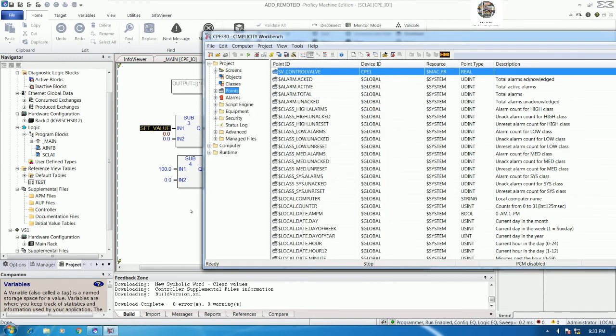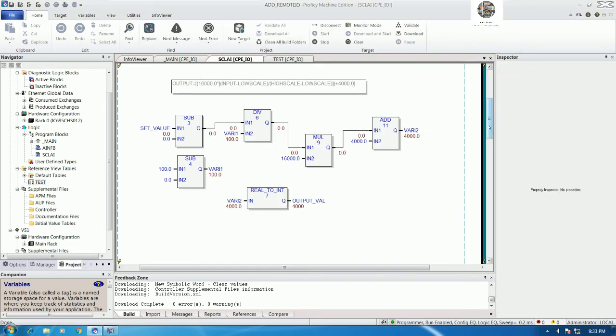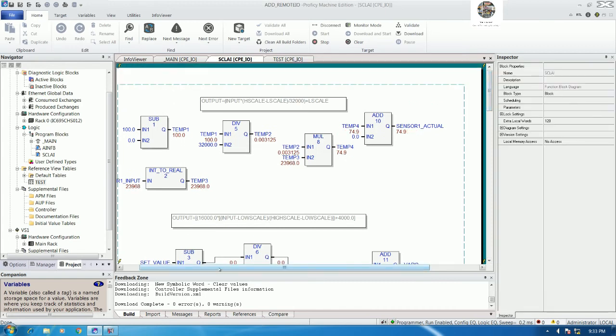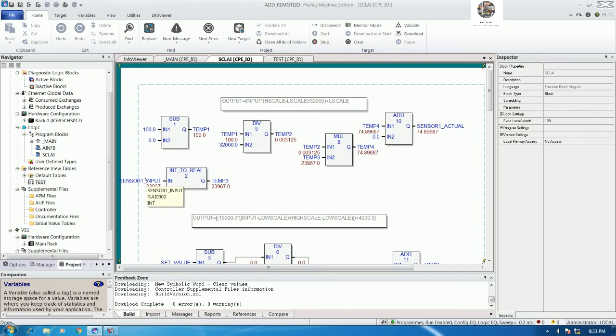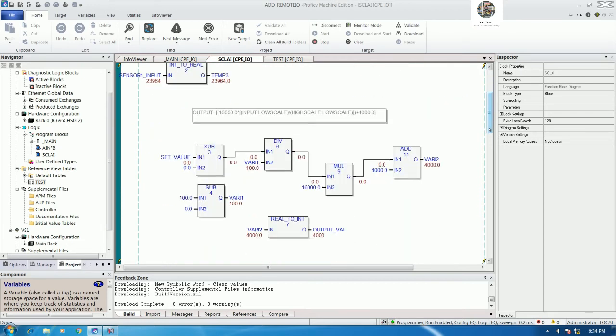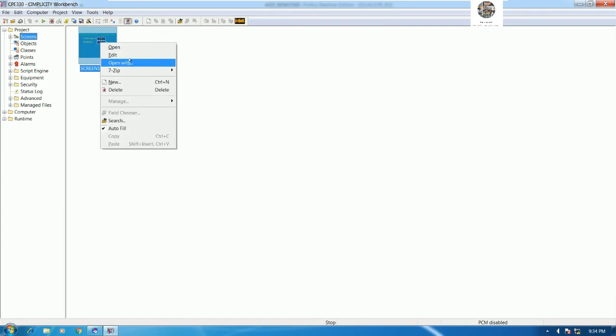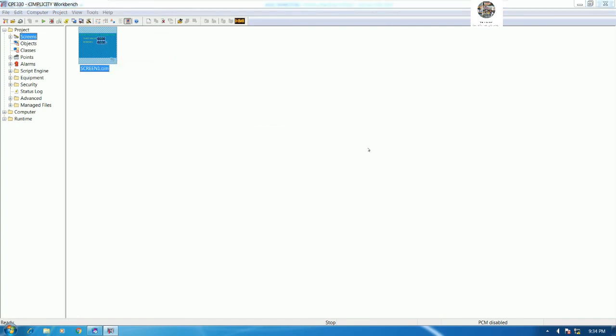And we need feedback from the control valve, right? So I will use AI1. So I will change this one to AI1. Okay, we can use AI2 because right now I already connected the loop control to AI2 and the scale is correct. So we can modify our screen, edit, and then start the project.